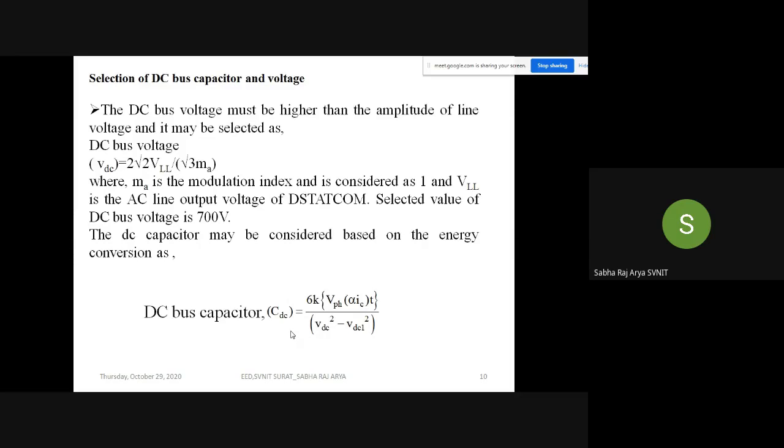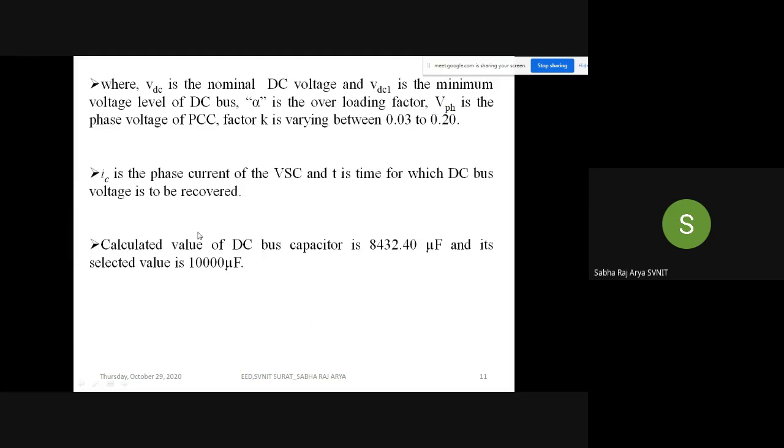Again, we are going to use electrolytic capacitors only, because only those are available in the high microfarad range. After that, we can also take somewhat of an overloading factor, as well as the energy variation due to dynamics. Those points we should consider. So our rough guideline is for each 5 kVA, we want 2000 microfarad.